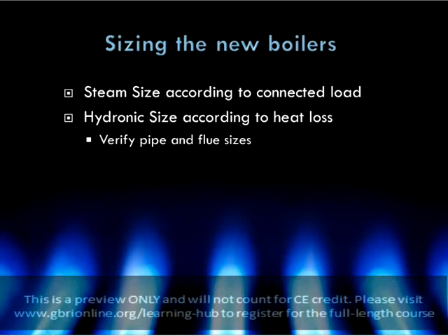Then you also have to factor in the piping that connects from the boiler up to the radiators or the fin tube radiation. In the old days, maybe 100 years ago when they were putting these in, that was about 50% more. For example, if you had 1 million BTU worth of piping losses, you would have to size your boiler for 1.5 million to meet that load.